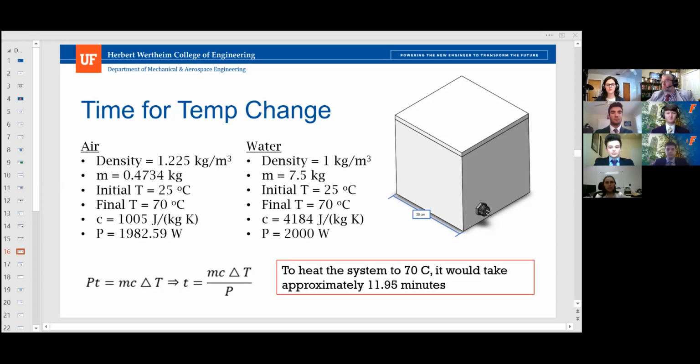Assuming an initial temperature of 25 Celsius and the 2000 watt immersion heater, it will take approximately 706 seconds or roughly 11¾ minutes to heat the water before it flows through the system. Once the tubing map has water flowing through it and taking considerations of the properties of air and the volume of the interior of the structure, it takes roughly 11 seconds to heat the interior, giving a total of approximately 11.95 minutes to reach maximum temperature of the interior.